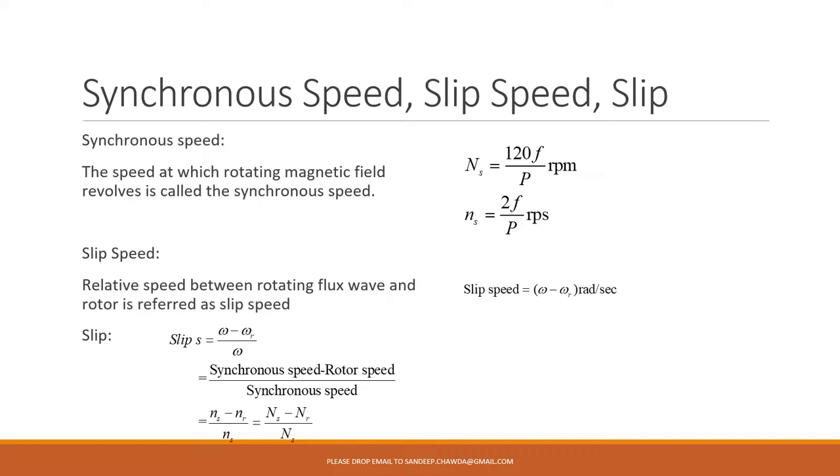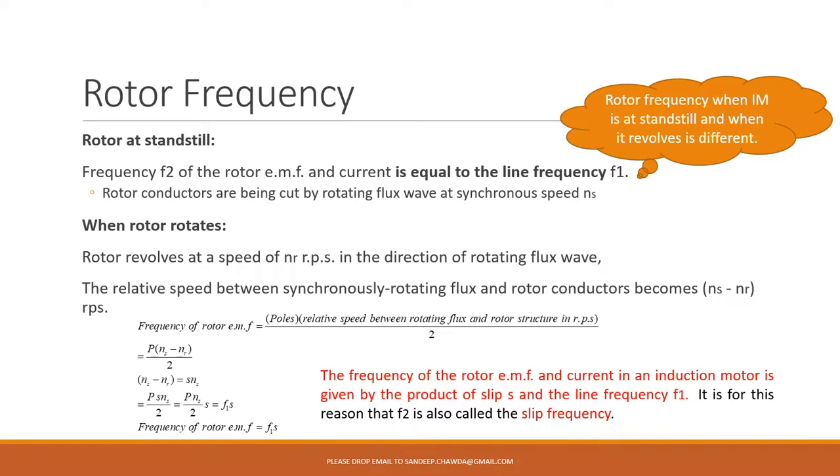We were talking about three-phase induction motor. We have seen certain relationships of induction motor, synchronous speed, and slip. We have also seen the rotor frequency at standstill and when it rotates. The frequency at standstill is supply frequency. Standstill means the rotor is not revolving, it is stationary. When the rotor rotates, the frequency becomes slip times supply frequency.